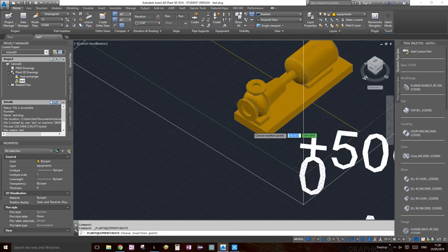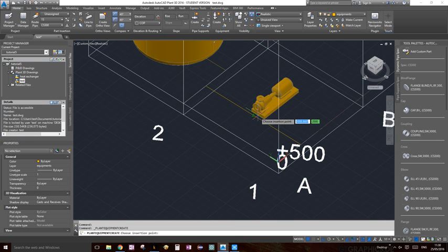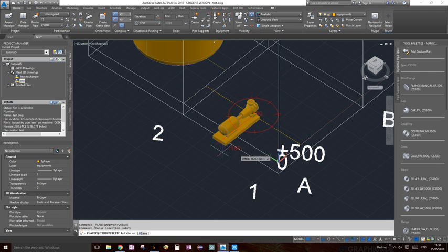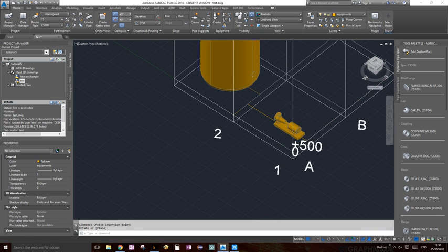So everything is good. Let's click on create. Now it's going to ask me to snap onto a point. Okay, so let's snap onto this midpoint here. Perfect. Now it's again giving me the option of rotating around our XY axis. Usually that's what it will do. So wherever your user defined XY axis is, it will let you rotate around that when you add a brand new equipment. So let's say we want it there. So just snap it from there to there and click OK, and it's added.